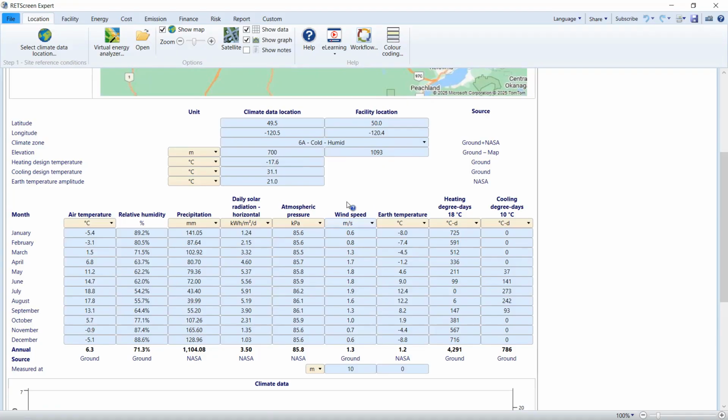We also have the wind speed, which we're obviously going to need. However, this wind speed is from Princeton, which is 60 kilometers away from our site. Clearly, we shouldn't rely on, at least without having very carefully analyzed it, wind speed information from 60 kilometers away. So this is not helpful for us.